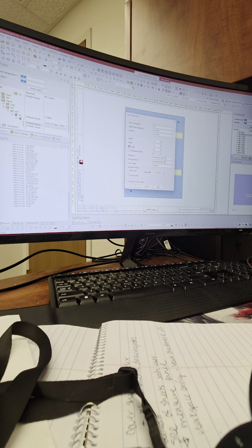The device nomenclature in this case for rails and ducts, to me at least, it's not very important unless you really want to call them out on your drawings. On your drawings, you want to see where your rail 1 is, rail 2 is. So your builders on the shop floor would know when you say, add relay to strip 1 or add relay to DIN rail number 2. Those references is where it kind of matters to make sure that people on the shop floor do it right the first time, if you will. Yeah. Okay.